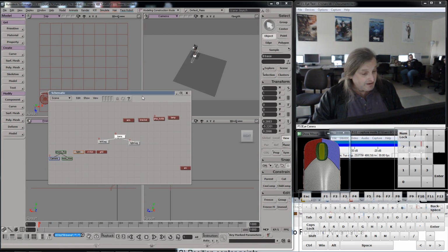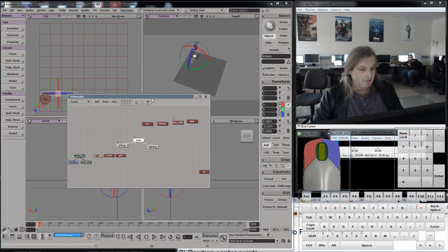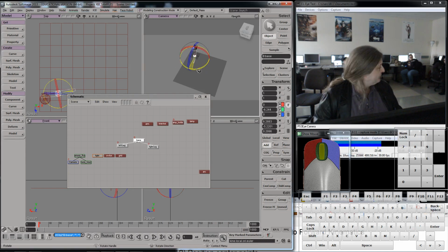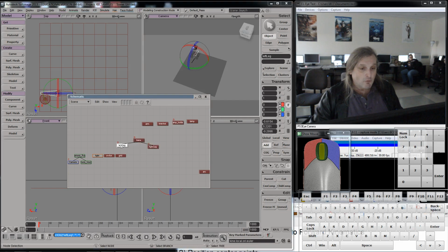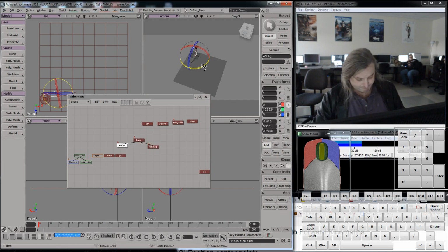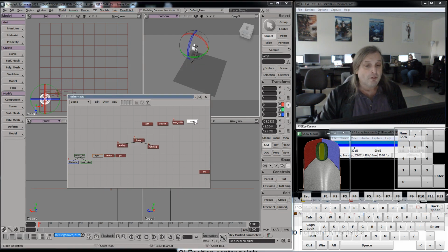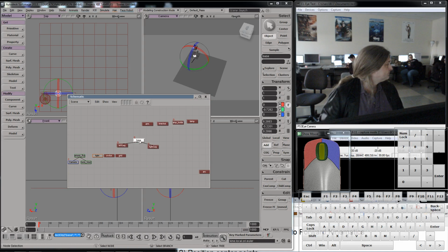And what that means, if I right mouse click, is that if I rotate, they all go together. See that? If I pick one of them, it will rotate appropriately to everything else. Control Z. I now want to put the lamp attached to the lamp holder, attached to the bracket, attached to the arm, attached to the base.